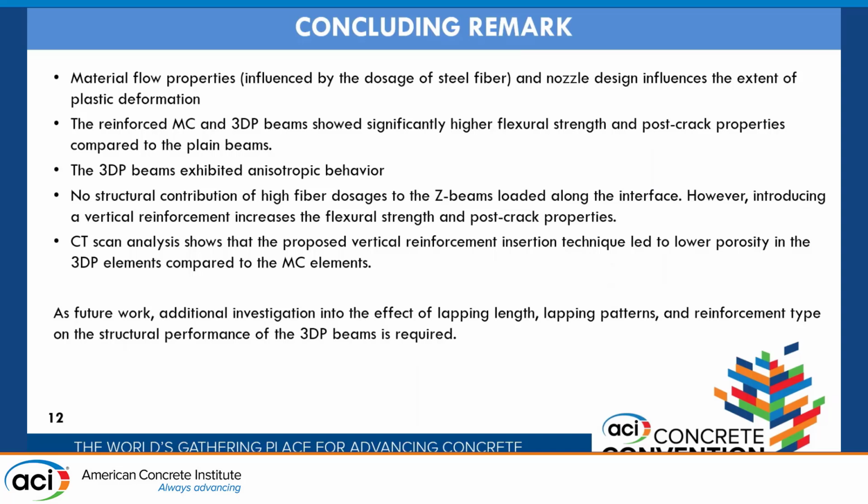So to conclude my presentation, our study has shown that different flow properties of the fiber reinforced material and also different nozzle design can influence the extent of plastic deformation during the construction 3D printing process. We showed that by adding up to 2.5% of fiber, we're able to significantly improve the flexural strength and also post-crack properties of the 3D printed elements.